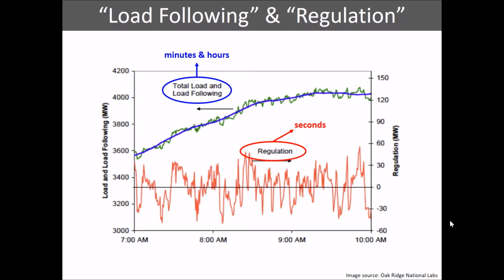So we're going to have some things, the red curve, that we could smooth out using storage. We could store at times when we've got slightly too little, and we could release at times when we've got rather too much. And we could smooth that out with a relatively small capacity of storage. In this case, our maximum up and down is, as I say, 30 megawatts in each direction. Clearly, to start to smooth out something like the blue curve, to flatten that out over long periods of time, we're going to need much larger amounts.